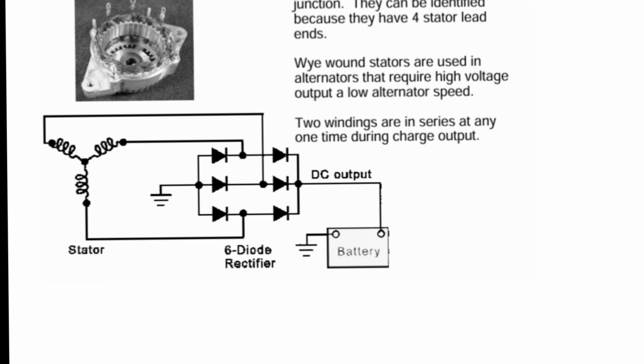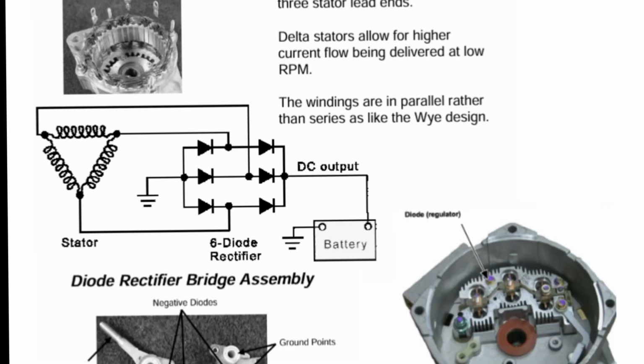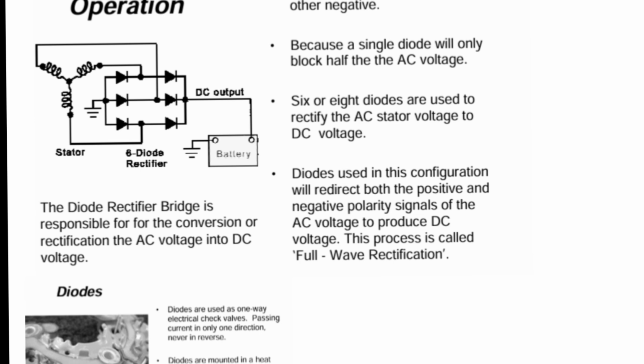Normally 4 wires are used in alternator circuits. B terminal, battery. Main charging output to battery. IG terminal, ignition. Ignition supply from key switch. S terminal, signal or sense line. Voltage sensing line for regulator control.